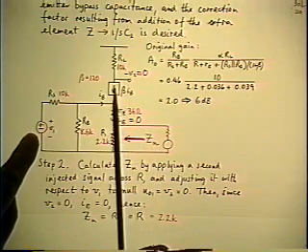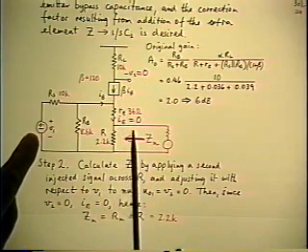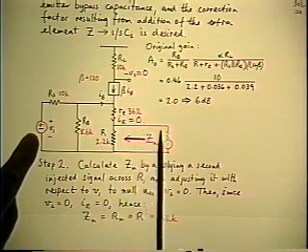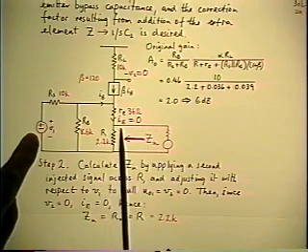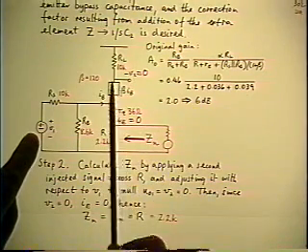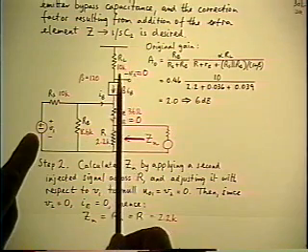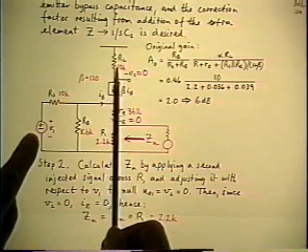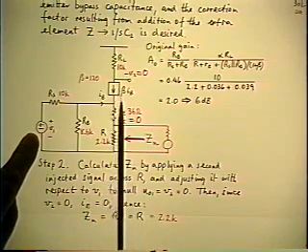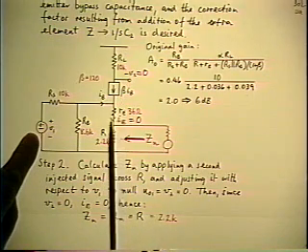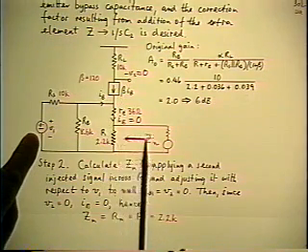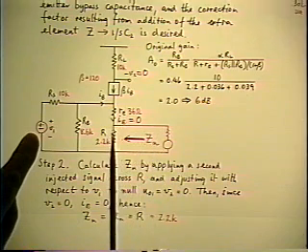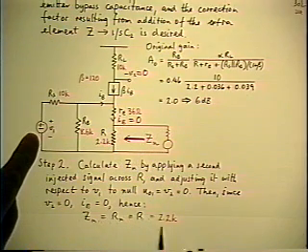You propagate the null back to the second source, because the objective is to find what happens to the current from the second source. Where does it go? And the argument is, if V2 is zero, zero current in RL, zero collector current, zero emitter current, and that tells you the answer you need. All of the current from the second source goes down R, so the answer is R.